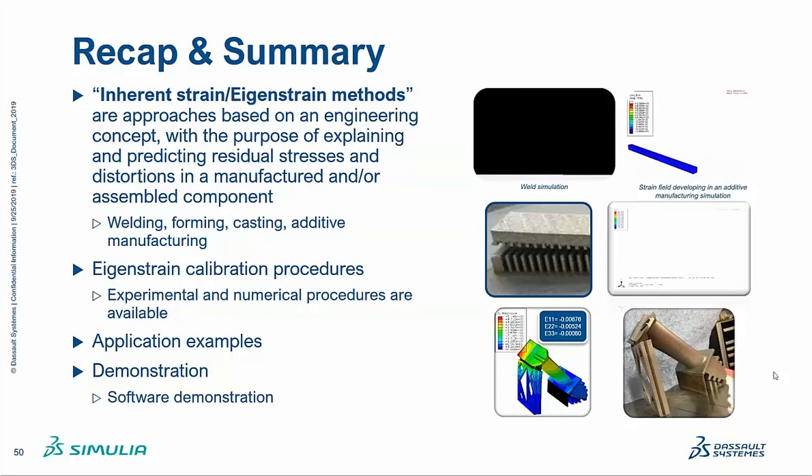The eigenstrain is an approximative method, and it makes life easier because, as we saw in the example of the weld simulation, the full-size ship is very hard to simulate in a full-scale simulation, especially in 1987 when the eigenstrain concept was devised. That was not possible, but today we have the option to run a full-size ship, but maybe want to do an estimate with the eigenstrain analysis.